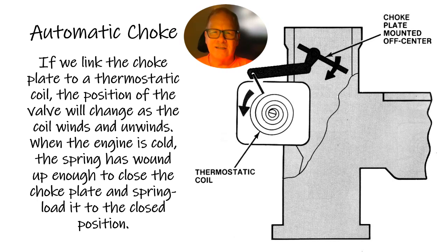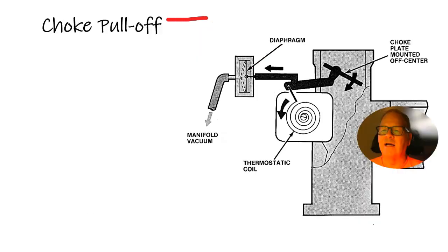They either used exhaust heat, or they'd use an electric signal from the stator winding on the alternator. You might notice on some of the Chevy trucks, when the alternator quit putting out, there'd be an orange light on the dash that would come on to say choke, because the choke actually gets its energy on a lot of those GM vehicles from the alternator stator, which only has about 7 volts. And the choke should be completely open within about 90 seconds if one's working right.